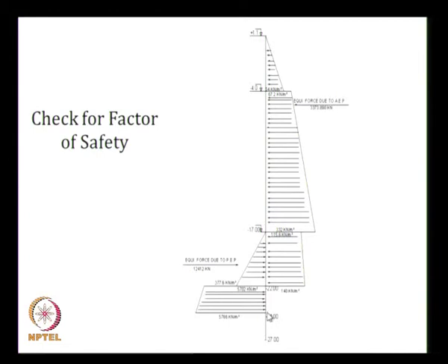You have to do trial and error to calculate this. When it is mobilized, it will not mobilize fully; it may mobilize something like this to create a force equivalent to this active earth pressure. You will have some reserve capacity. The structures which have failed do not have this reserve capacity because they have not taken the diaphragm wall into the rock; they have stopped here, we have taken it into the rock. What is the factor of safety here? 2 times.